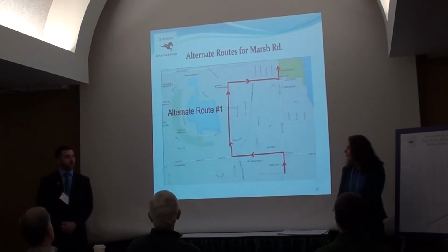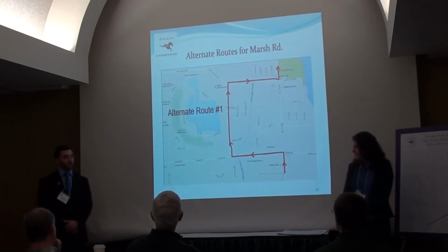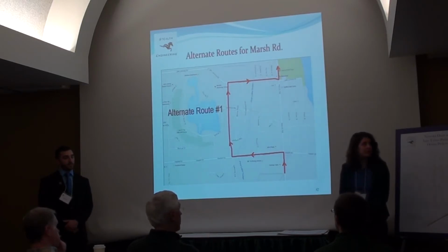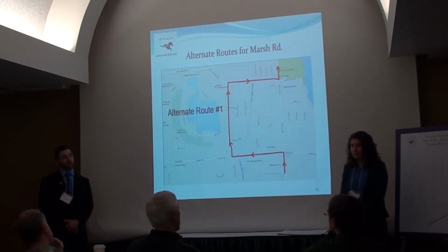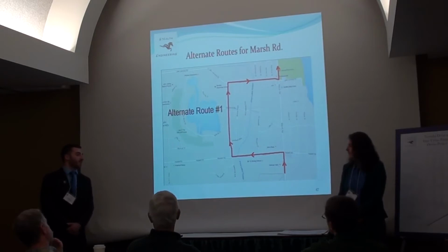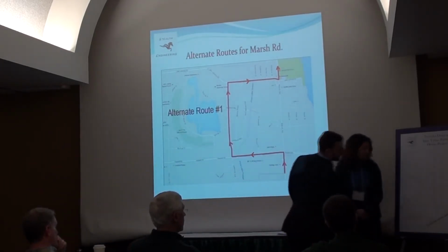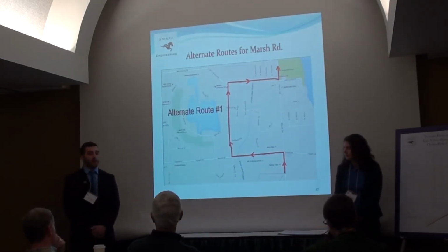Something to be considered with that 66 feet given for the road right of way: all the swales fall well within that 66 feet. So they're all public, and they would all be in the public right of way. Yes. Are sidewalks being proposed for all streets? Yes. With the exception of some sidewalk that exists on the east side of Shaw that was determined to be in good condition.